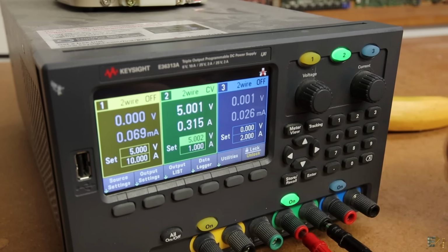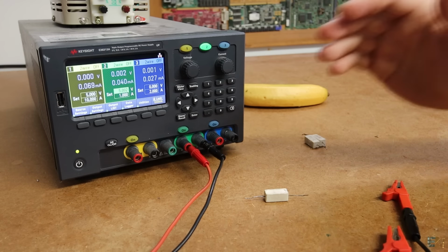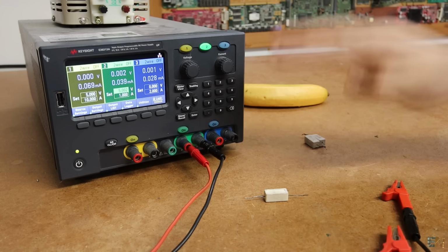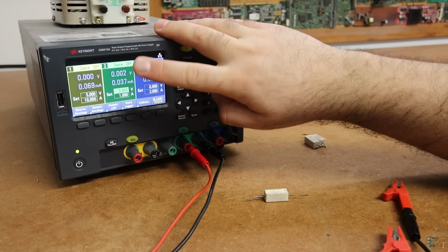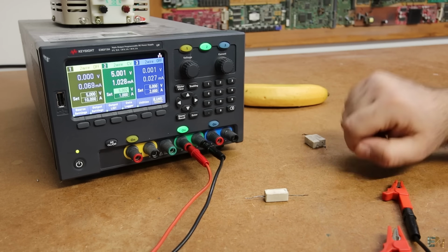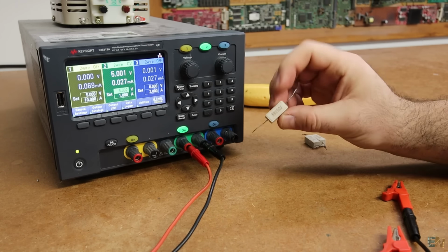fix a voltage and then increase the current. You will see that the voltage will drop. Okay, so you will see how easy it is to understand this. This is my power supply. I set the voltage to 5 volts and the maximum current output to 1 amp. I activate the output, and to simulate a load, I'll add just a resistance like this one.